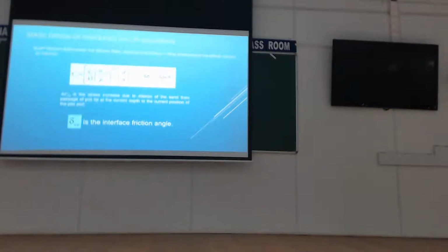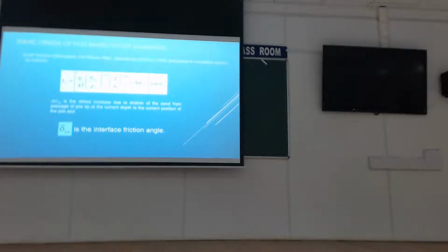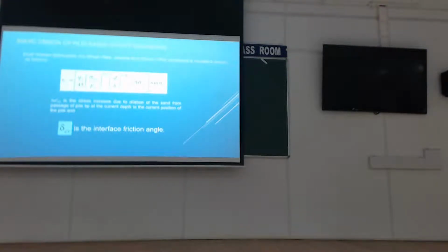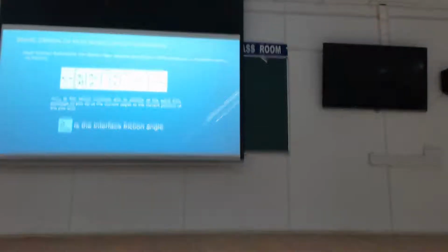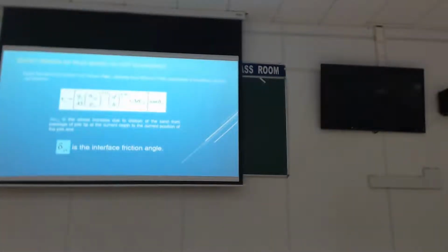One good thing they do is they take the vertical effective stress and normalize it with the atmospheric pressure. So this PA here is basically 100 kPa, which is 1 bar of atmospheric pressure. So you normalize your vertical stress with atmospheric pressure, so that becomes dimensionless. Also, you normalize the depth at which you are with the total height of the layer. So D over H is also dimensionless. And then you get these factors because they're fitting curves. Then you have this extra bit here.